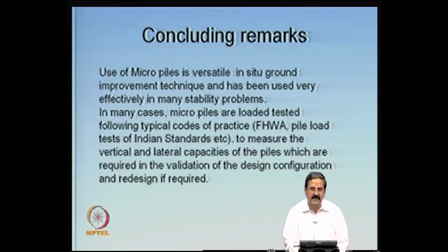Then when they did the SPT tests, earlier they had taken 20 ton per meter square as the bearing capacity and went ahead with the design, but the investigation showed that the bearing capacity was only 7 ton per meter square. So, they have to make it up so that 20 ton per meter square is available, otherwise they cannot go ahead with construction.